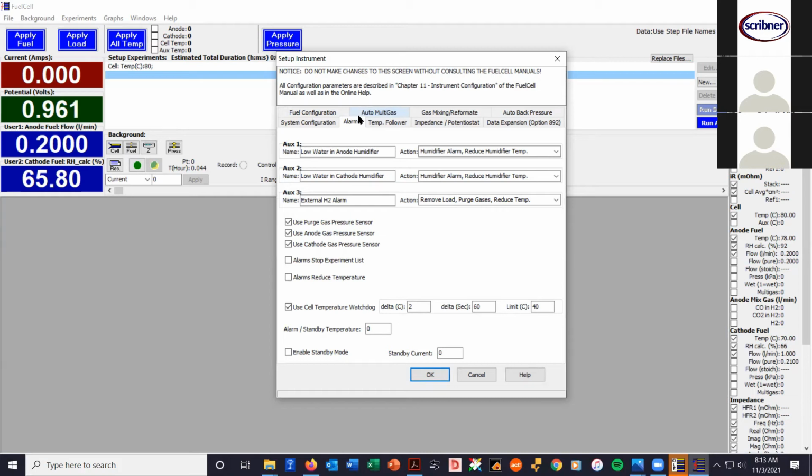And that means you can end up putting a lot of heat into those heaters and damaging them and the insulation prior to even registering a temperature change at the thermocouple, because it's in air or a gas, which is a relatively poor thermal conductor, as opposed to water, which is a fairly decent thermal conductor. And so you register that temperature rise relatively quickly. So all that is to say, you don't want to apply temperature or try to heat up an empty humidifier. So the humidifiers have water level sensors in them, essentially.